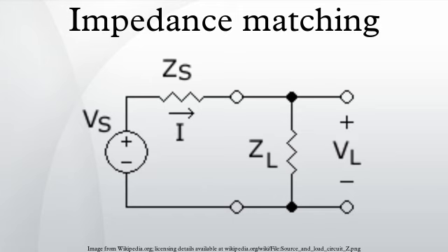This issue was addressed by the step transmission line, where multiple, serially placed, quarter-wave dielectric slugs are used to vary a transmission line's characteristic impedance. By controlling the position of each element, a broad range of load impedances can be matched without having to reconnect the circuit. Filters are frequently used to achieve impedance matching in telecommunications and radio engineering.